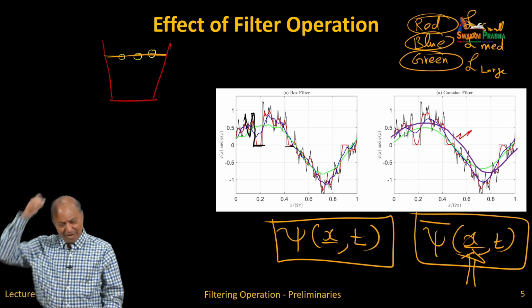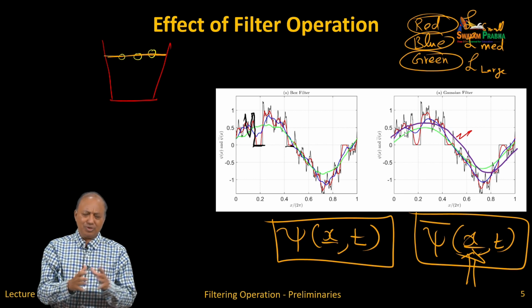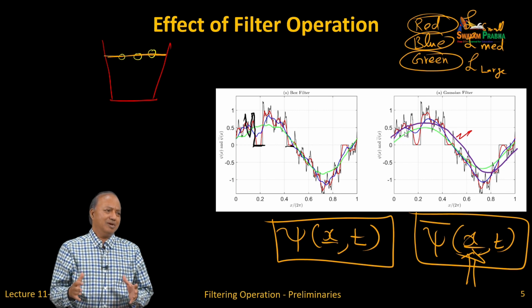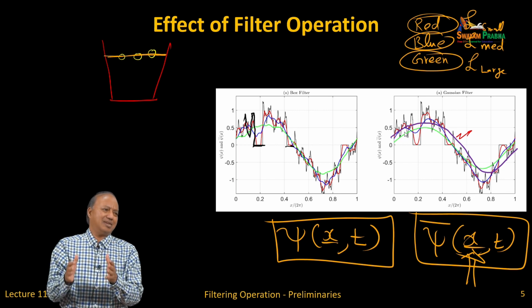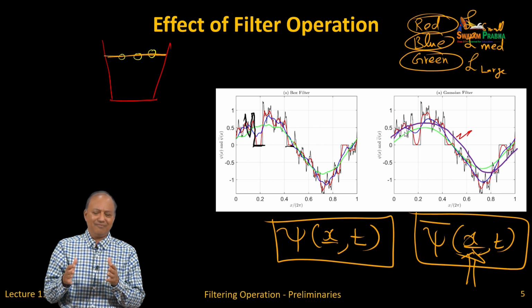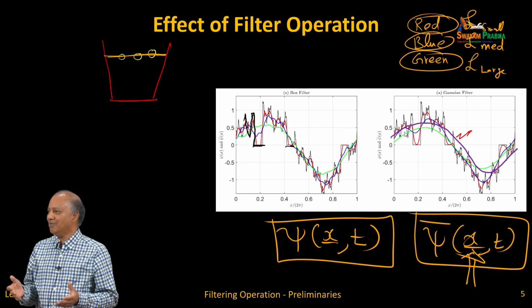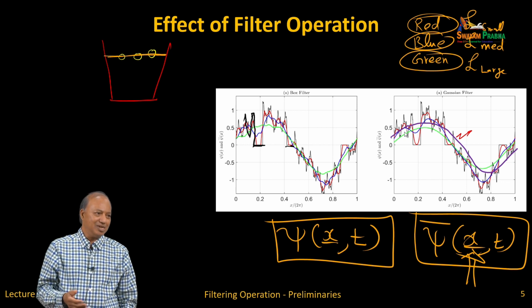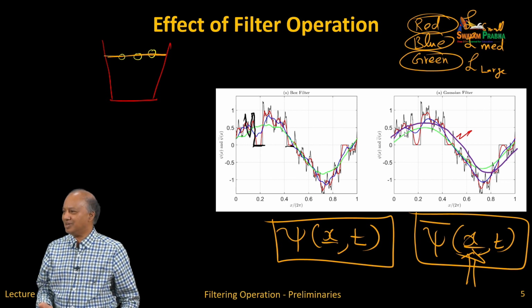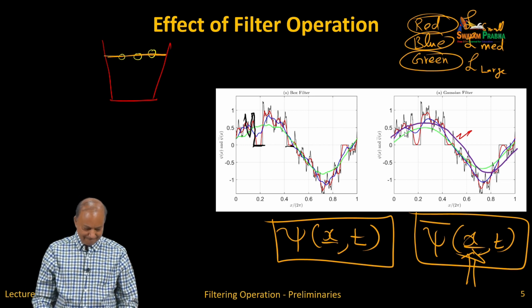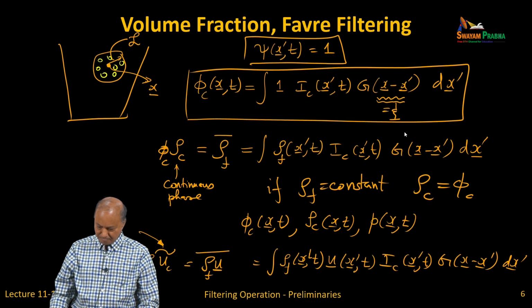But other fluidized bed, etc., one would need to choose, if you are doing Euler-Lagrange or Euler-Euler, you should choose a grid which is fairly bigger than the particle size, maybe at least 5 times, 10 times bigger, so that you will have a good number of particles inside your cells, so that when you use average drag it makes sense, etc. Okay.